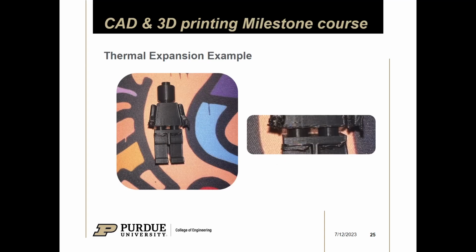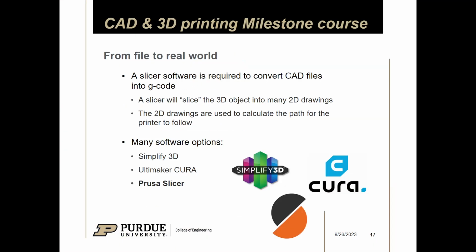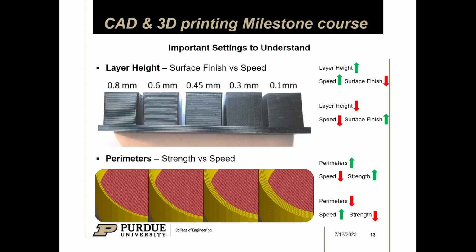I guess I forgot to add this. The one thing to consider when you're modeling is layer orientation. On the layer height photo, you can see all the print lines of the layers, and those are actually points of failure. If you ever have a print in a high stress environment and the print breaks, it often breaks on the layer lines.